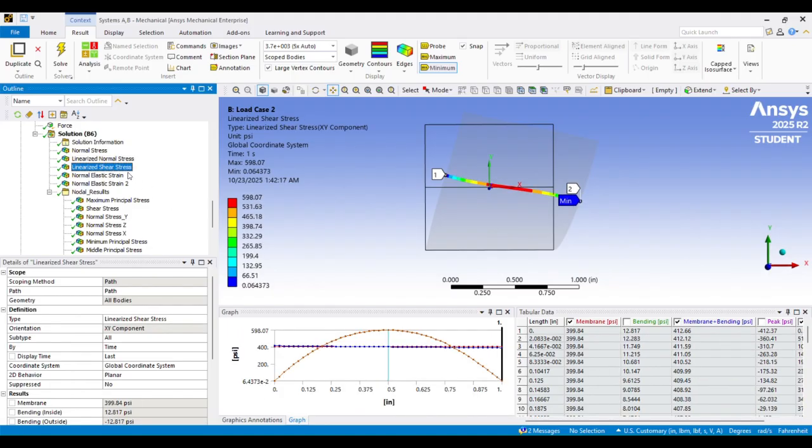And I also looked at the shear stress through the part. And if you remember from your shear stress calc, you can actually calculate this shear stress. And this is what the profile would look like if you did it by hand. And you see that there's a maximum shear in the center, and then it goes to zero at the top and bottom of the beam.